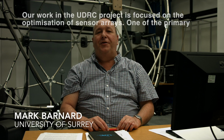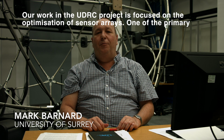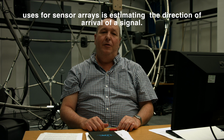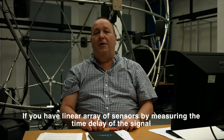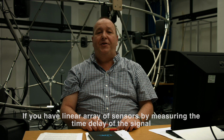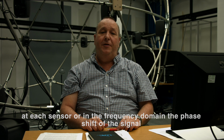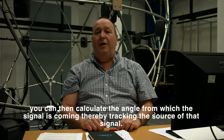Our work in the UDRC project is focused on the optimisation of sensor arrays. One of the primary uses for sensor arrays is estimating the direction of arrival of a signal. So if you have a linear array of sensors, by measuring the time delay of the signal at each sensor, or in the frequency domain, the phase shift of the signal, you can then calculate the angle from which the signal is coming, thereby tracking the source of that signal.